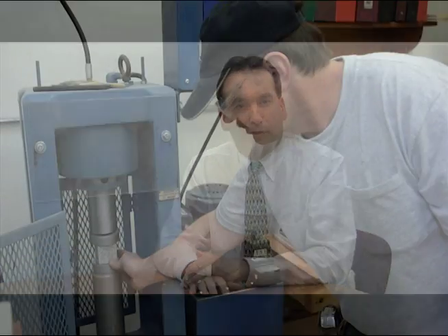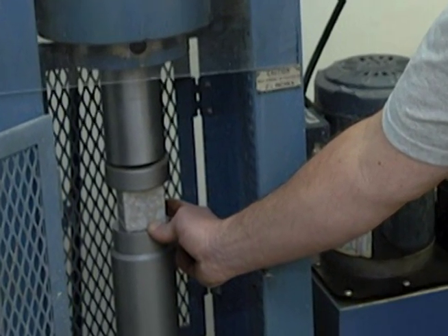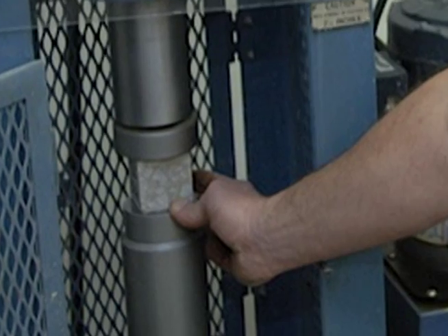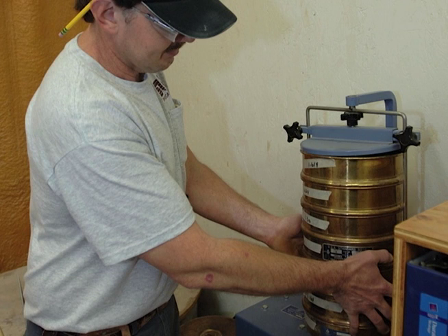The product testing is pretty involved. Our members are actually required to test their product for every 500 cubic feet of material that they produce. They are testing the material for compressive strength to make sure that it meets 6,500 psi. They're testing it to make sure the absorption is less than 6%. They're even testing their product to make sure that it passes freeze-thaw durability test. Again, all of those are really aimed at making sure that it's a premium quality product that is going to sustain itself over time.